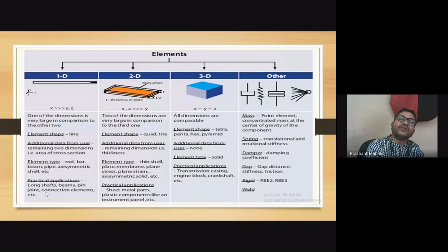So at the time when you are in the job, you must remember this practical application, so that at that time you will decide on your own which element to use. When you are going to go for analysis of long shafts, beams, pin joints, connections, etc., then you have to use 1D as the element.